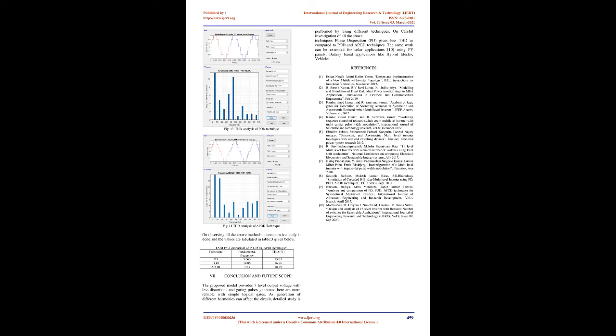Simulation results. The proposed multi-level inverter is designed with the help of MATLAB software as shown in the figure 8 below. The gating pulses to the above circuit can be given by using PD, POD, APOD techniques with the same load. However, irrespective of any technique, the produced gating pulses will be almost similar. The gating circuit along with gating pulses are as shown in the figure 9, figure 10 below. From the designed MLI, the 7-level output voltage is obtained as shown in the figure 11 below.